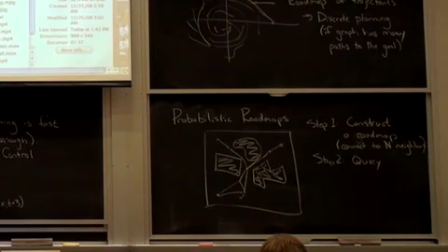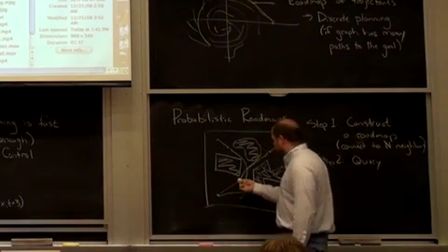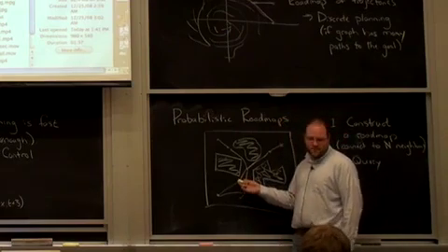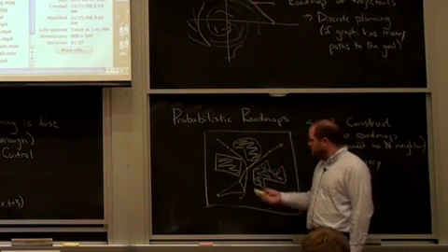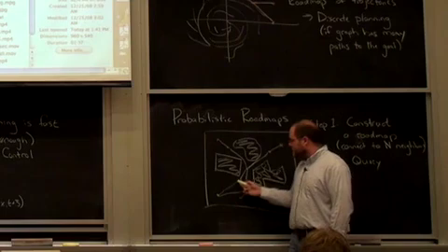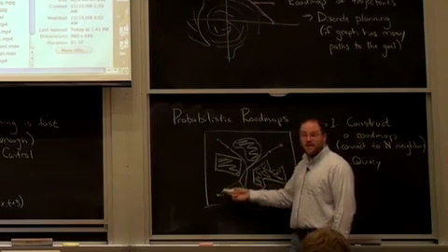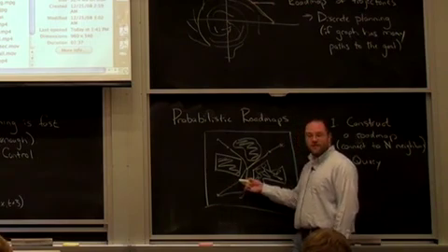Now with probabilistic roadmaps, again, this step of connecting nearby points in underactuated systems might be hard, might be as hard as finding the path from the start to the goal. So maybe what you do here is actually do a DIRCOL or something to find that path, or you do an RRT, or any of the other methods we've done to make these initial connections.